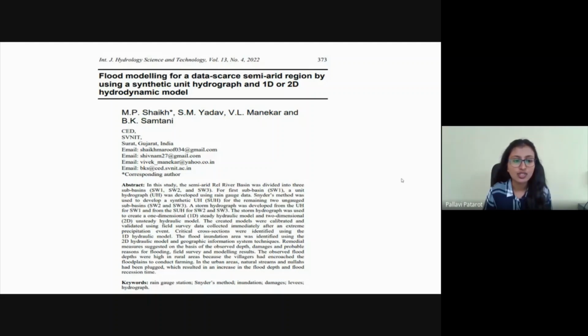The HEC-RAS software is a one-dimensional and two-dimensional hydraulic modeling program that uses four types of river analysis: steady flow models, unsteady flow models, sediment transport models, and water quality analysis. Its major purpose is to perform flood studies and define floodable areas by simulation of flow in natural riverbeds or constructed channels to assess the water level, which we have seen in our hands-on session.